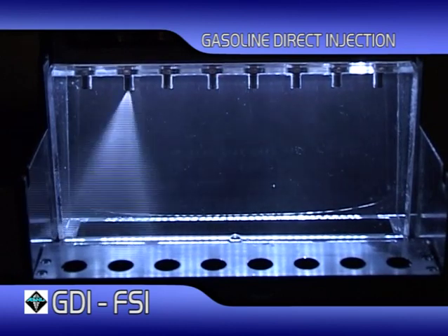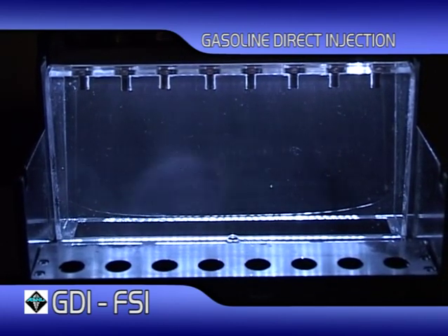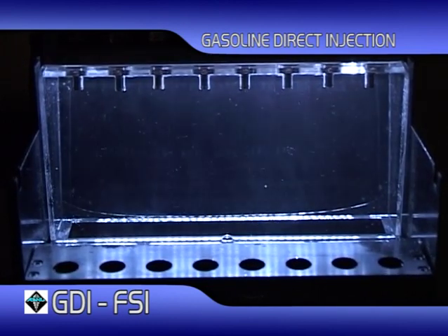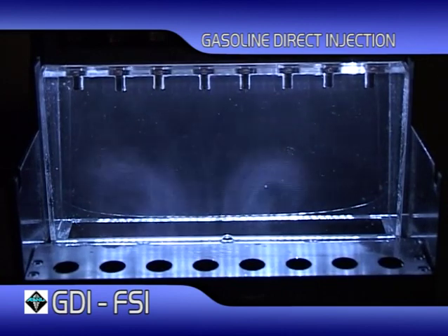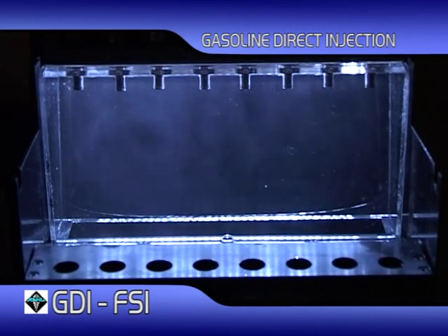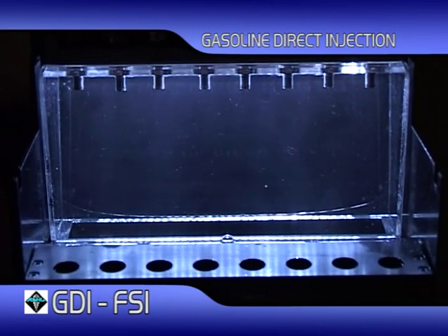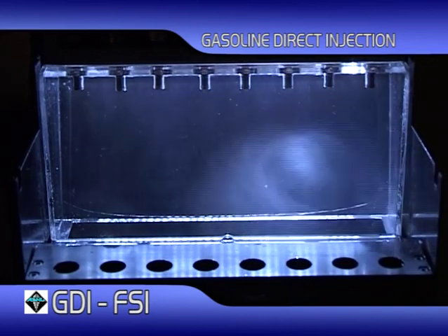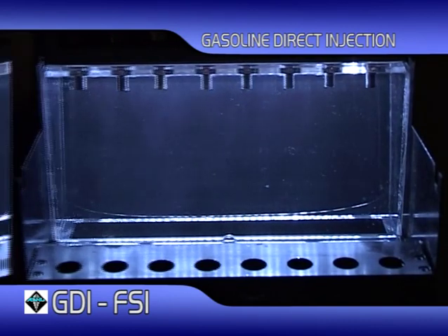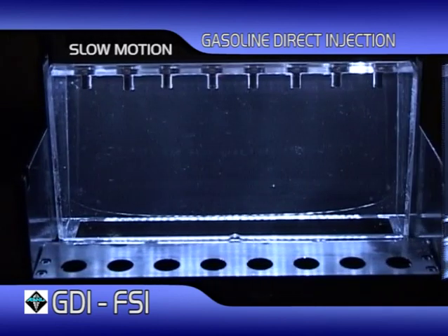The correct spray pattern for the designated application is critical, and therefore it is paramount to ensure that all the injectors have the same spray angle and fuel droplet formation. The location of the injector in conjunction with the shape of the piston will determine the required shape of the spray pattern. The wrong spray angle and the fuel will not mix with the incoming air, the process of correct combustion will fail, and the lambda control will take action to correct the problem, taking drastic action to protect the system if required. To help show this better, we have slowed down the clip of these injectors spraying.